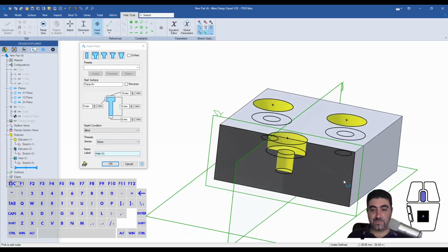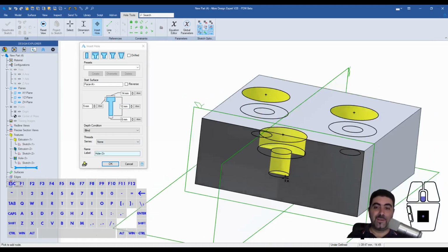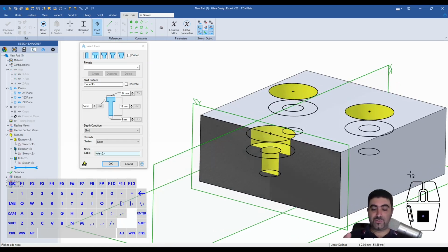Okay, that's all well and good, but you can't really drill that. That has a flat bottom. So when you're making that in the machine shop, in order to get that exact shape, you need to drill it with an end mill, right? Basically. So if you actually drill it with a drill, you'll get a cone down here.